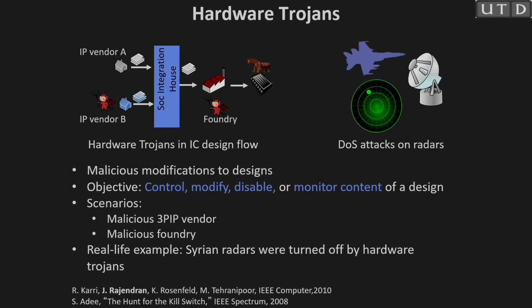And there are two types of hardware Trojan. One is basically leaking sensitive information, that might leak some sensitive information, or it might modify the circuits also, right. And basically this hardware Trojan gets activated in very corner scenarios, right. Like, if the input is a specific pattern, then only this hardware Trojan will be activated, or say it will be activated after 1 year, right. So, this kind of trigger condition is something, it is very corner cases.